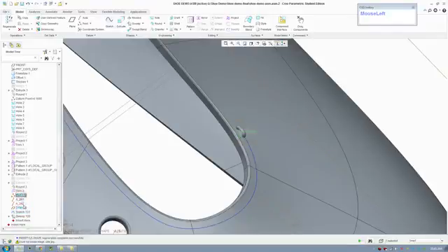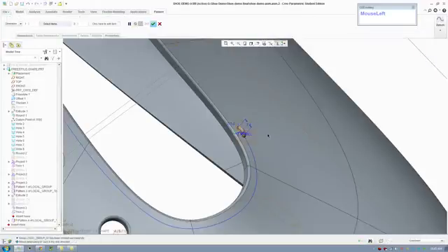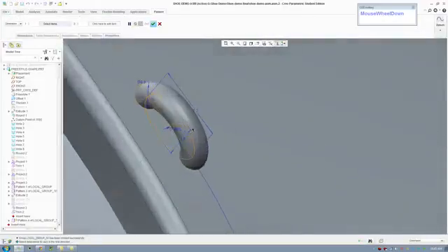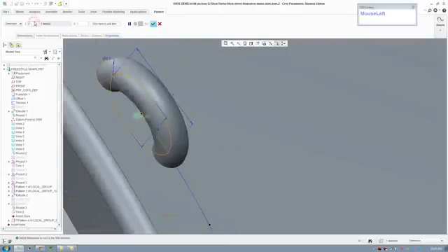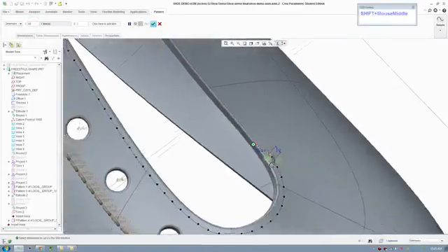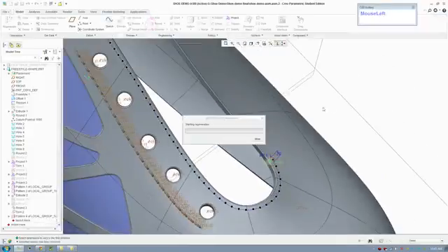So actually you can group the whole thing in and then go pattern, but when you do this, make sure you click the relative dimension, so it switches to relative, and make that 0.02, and I'll put that in as 50, I think, and click OK.